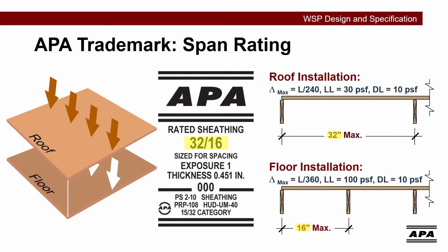Except for APA-rated siding and rated sheathing panels used as wall sheathing, the span rating is based on typical roof and floor loading. Roofs are considered to have a deflection limit of L/240, with a 30 pound per square foot live load and a 10 pound per square foot dead load. The floor span ratings are based on a deflection limit of L/360, 100 pounds per square foot live load, and 10 pound per square foot dead load.